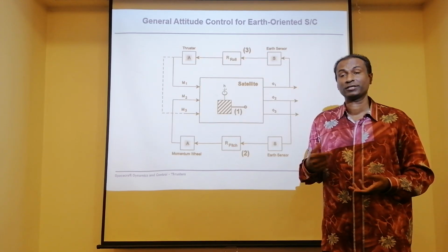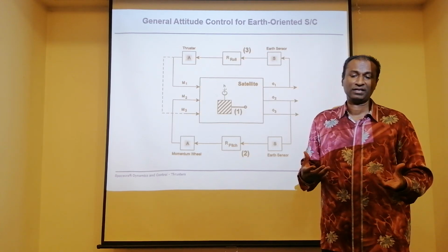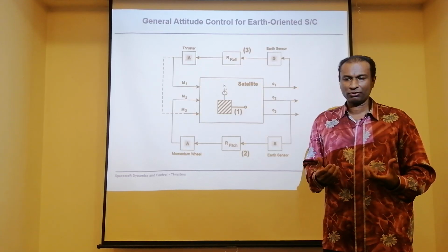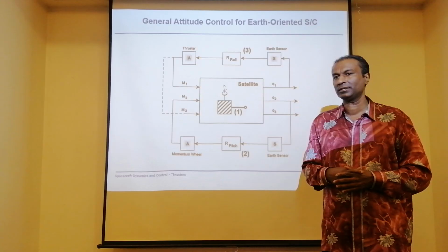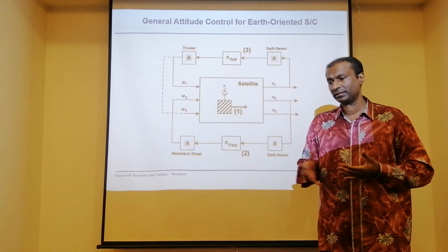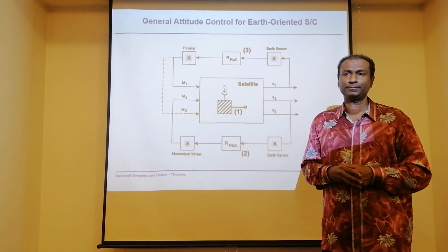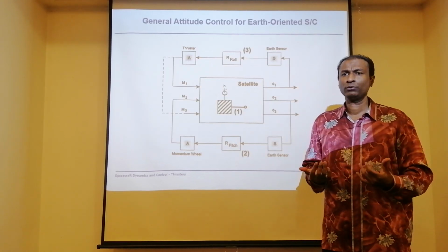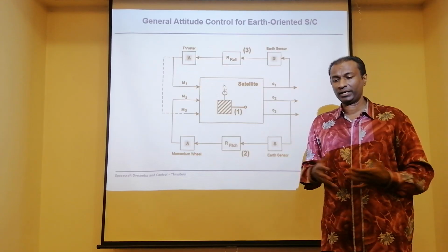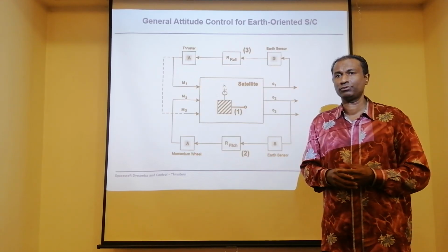Expensive in terms of you need to power the torquers and have the device. Then that's not good enough, because it gives a very high amplitude in terms of attitude. And you embark the options of the rotational actuators, the reaction wheel and the momentum wheel, and/or. And you have found that it is fantastic. It is giving very good results.